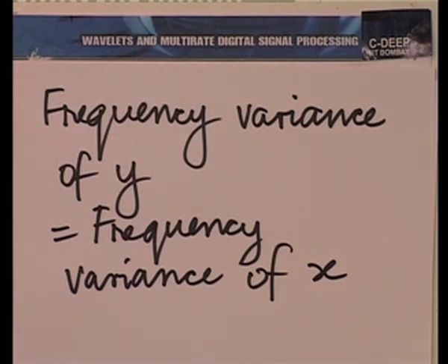So far, so good. We have taken two dual operations, the time shift and the frequency shift, and in both of them we have had no change in the variances. And obviously, when there is no change in the variances, there is going to be no change in the product of the variances. So, the sigma_t squared, sigma_omega squared product, which we shall now give a name, we will call it the time bandwidth product.